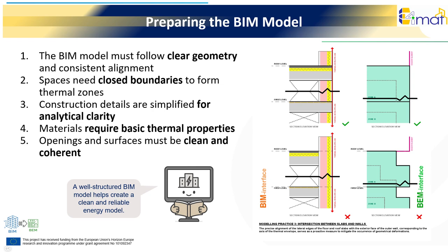For the analytical model to define thermal zones, each space must be enclosed by complete room boundaries, even if those boundaries are simple. Some construction details that are important for documentation are not needed for energy simulation. These elements are often simplified so that the analytical model can focus on what affects performance, surfaces, materials, and thermal connections.